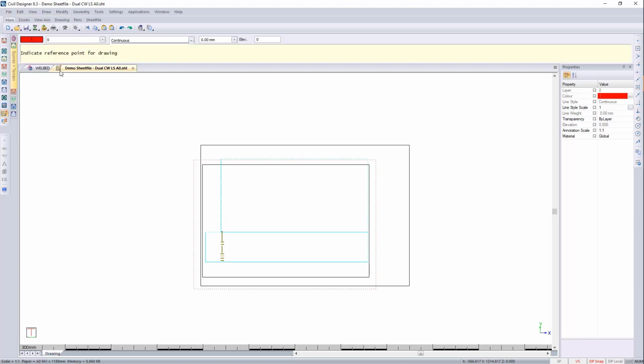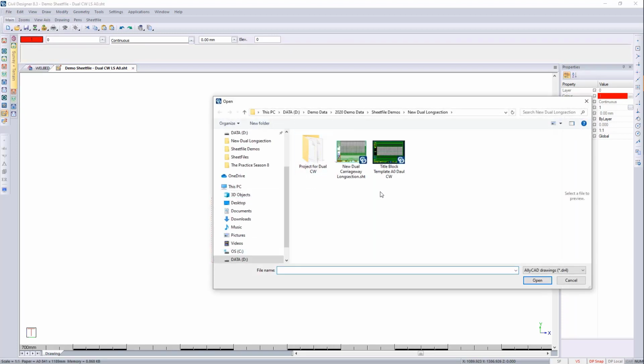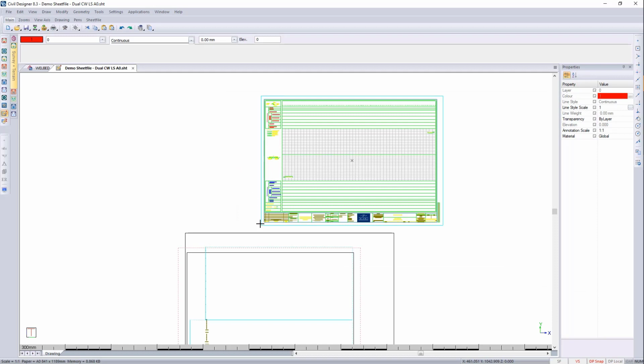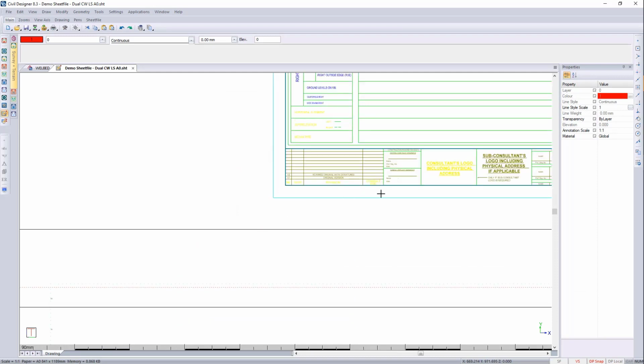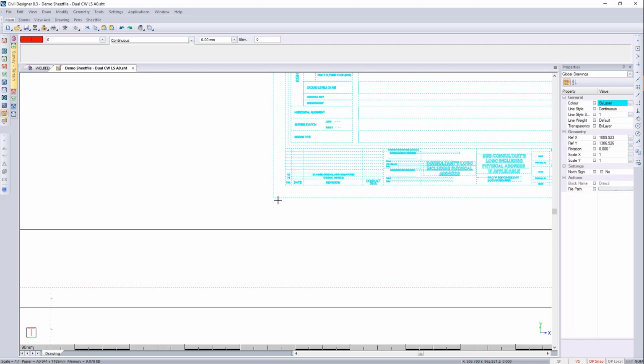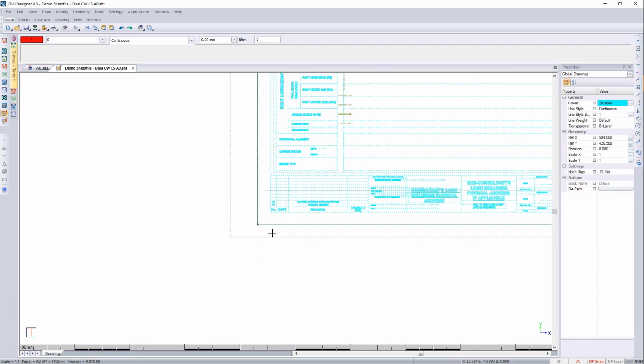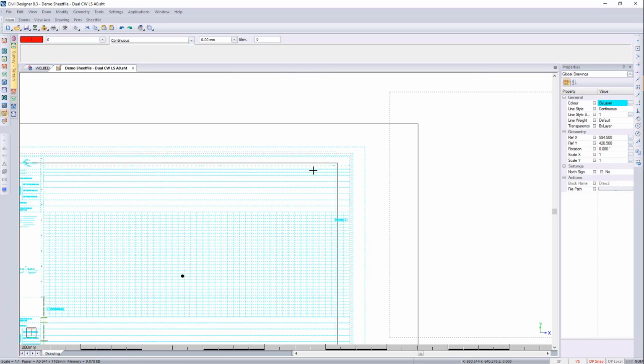So I'm going to go and load the drawing. I can actually just place it anywhere for now, and I'm going to load the title block into my sheet file. So I've loaded it anywhere because I wanted to see, you see why it's beneficial to know where that paper edge is. That's why I prefer having the paper edge in CAD. And I'm going to go and say modify move, and I want to use the snap. Click on that edge, and I'm going to move it to that corner. So now I'm happy that that edge is moved.